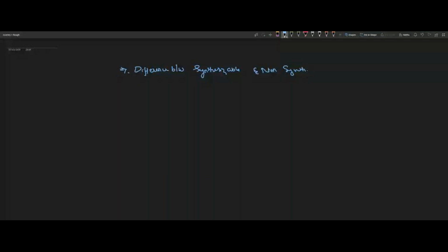So can you give me some examples which are not synthesizable? Fork-join, hash functions, delays, including a delay in the main program. You might have written initial begin, for initialization and all, in the test bench. Whatever is inside the initial begin, we write for test bench purposes, like a hash delay. We'll give a hash 10 millisecond delay in the test benches. Those are just used for simulations.